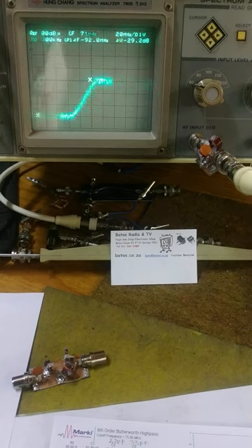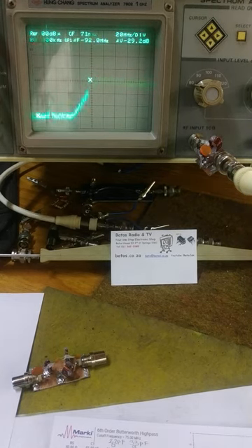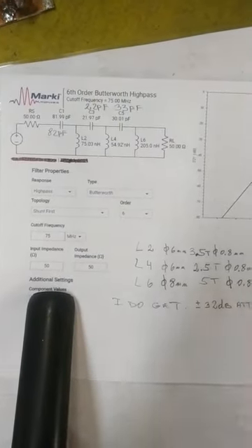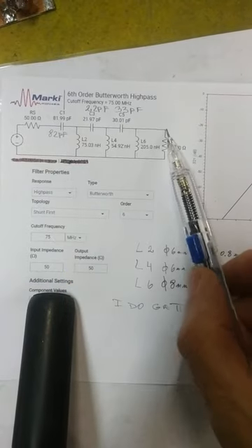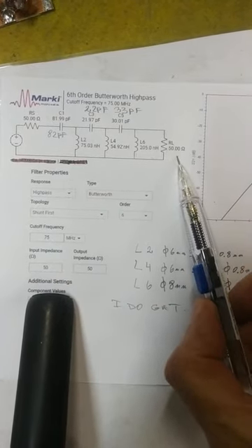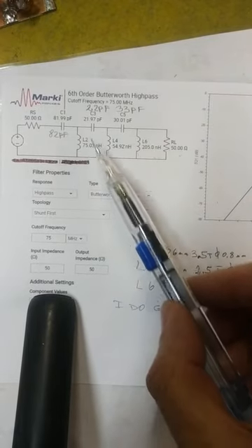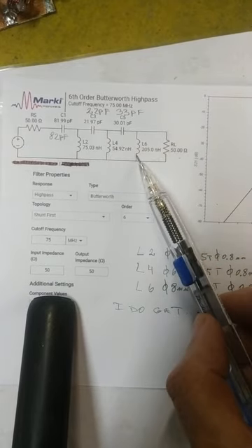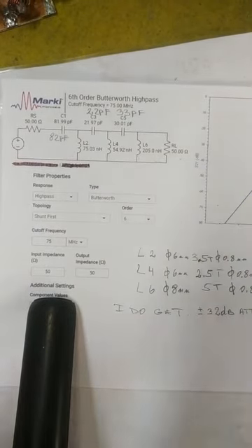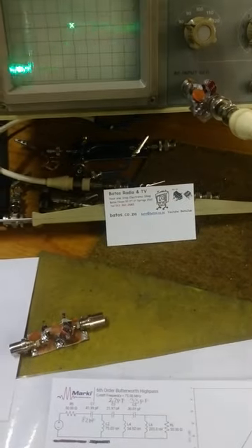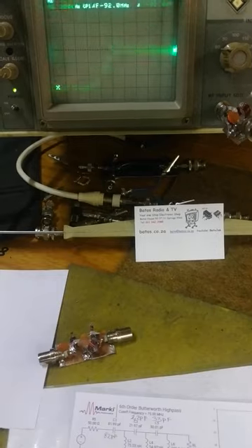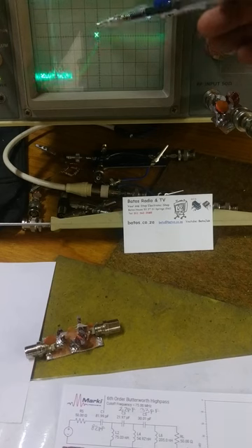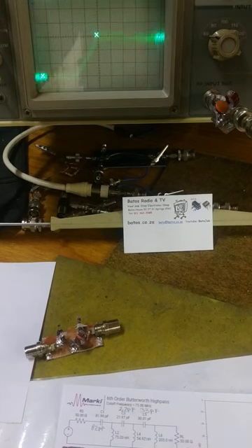On that note, I summarize the high-pass filter, and you can see the schematics over here one more time. That's the generator, that's my spectrum analyzer, which is 50 ohm. These are the components that I have designed, and I made the coils precisely and trimmed them by plug and play and measurements, so I can get a very high accuracy with the cutoff point at 75 megahertz.